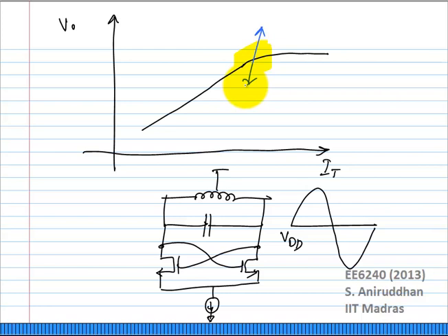If you increase further, what happens is this. Okay? Apart from these nonlinear effects where you might get clipping, there will be a certain residual DC voltage across the varactor and so on. Apart from that, what you find is you are increasing the energy. So if you actually move down this curve, you are increasing the energy you are putting into the system. However, the signal energy is not increasing. Right? So the majority of this will actually end up going into noise. You are increasing the noise. Obviously by increasing IT, you are increasing the noise, probably from the current source and the cross-coupled pair. However, you are not getting any signal gains back. So it is a very bad region to operate in. Okay? So for any VCO, the knee region is the best region to operate in.